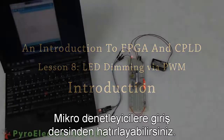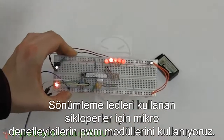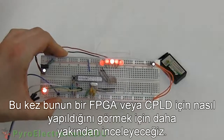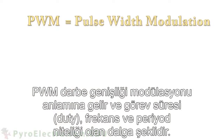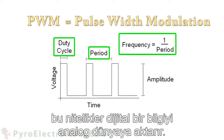You might remember back in the Introduction to Microcontrollers course, we used a microcontroller's PWM modules to make a Cyclops eye using fading LEDs. This time, we'll take a closer look to see how it's done for an FPGA or CPLD. PWM stands for Pulse Width Modulation, and it's a type of pulse with three attributes: duty cycle, period, and frequency. These attributes convey digital information in an analog world.